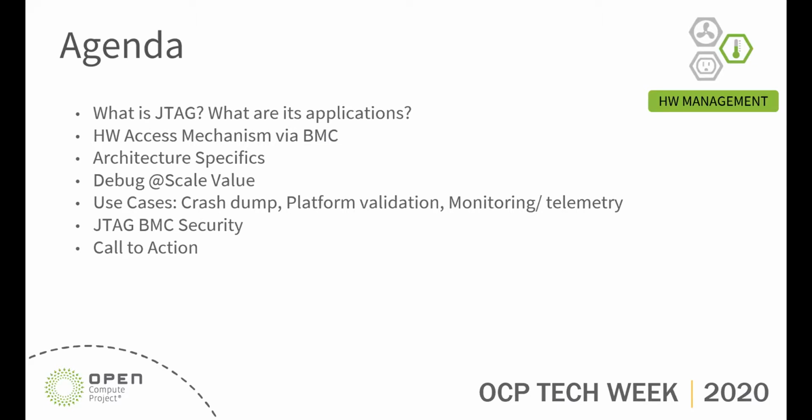We'll look at the architectural specifics, hardware, firmware, and then spend a little time looking at the value. Why would one go about embedding JTAG right into a BMC? It really revolves around the fact that you then have an embedded debug agent within the platforms. So essentially, debug at scale capabilities are brought to the table. Then we'll dive into a few of the many use cases: crash dump, some platform validation examples, and then application of JTAG for monitoring and telemetry services.